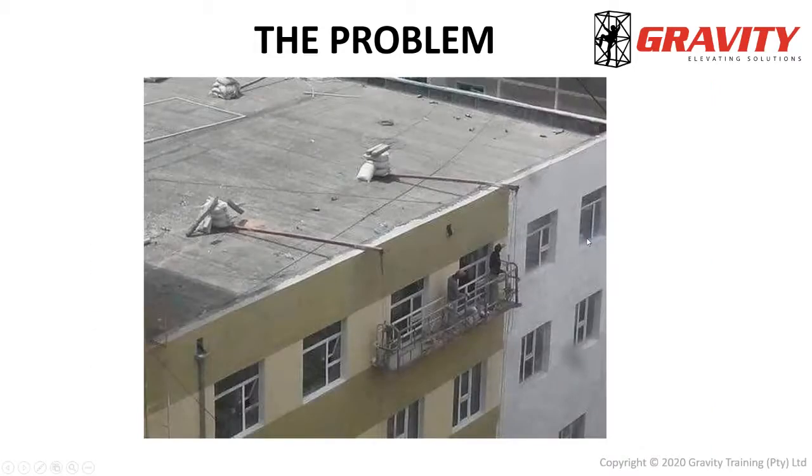And then this one, perhaps one of the worst ones, is these window washers improvising an anchor for a temporary suspended platform, or a TSP, by using these rods or beams with deadweight anchors on top. Now, again, most of these solutions do exist. Deadweight anchors is something that is allowed to be used, but again, any form of anchoring that you use should be certified, tested, inspected by competent people. Improvised solutions like this pose a significant risk to the users and to the public at large.